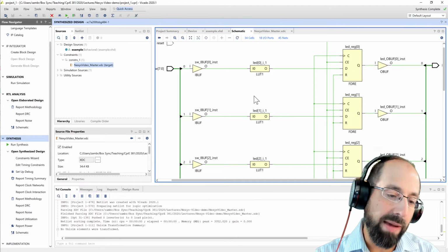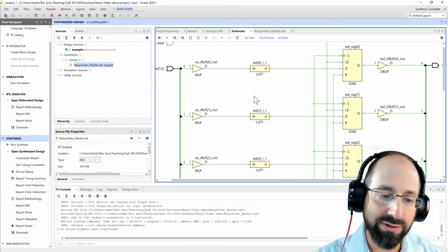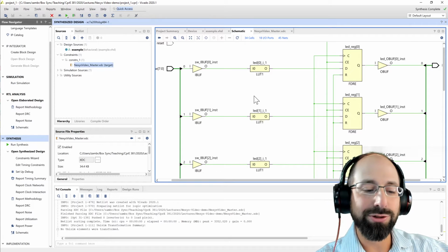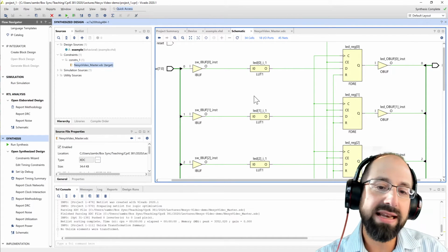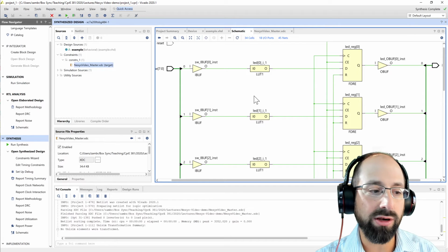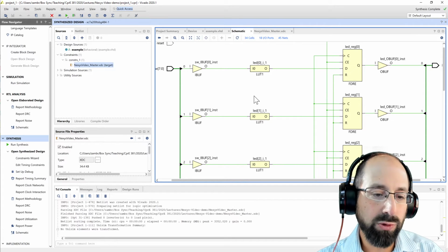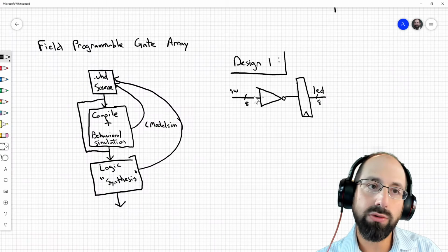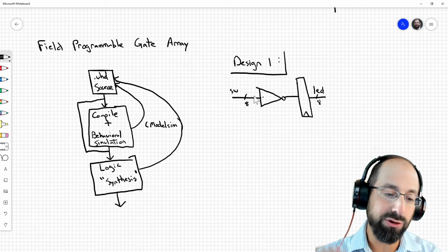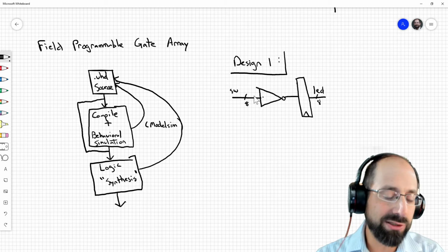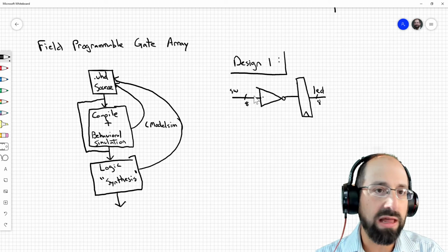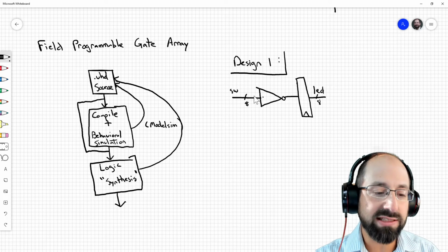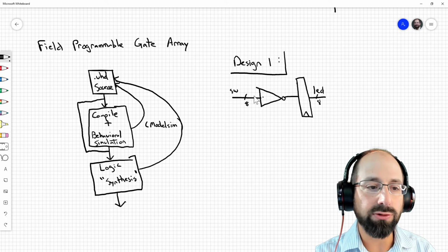You told me that all the paths basically have to fit within 10 nanoseconds because we constrain the clock to 10 nanoseconds. And did you succeed or not? Did everything fit within that 10 nanosecond window? Synthesis will give you a hint if that is the case. It'll tell you that either the design may not fit because you use too many lookup tables, we're at no risk of doing that today, or too many flip flops or too many other things. But it'll certainly tell you, based on an early estimate, what your critical path of design is going to be.